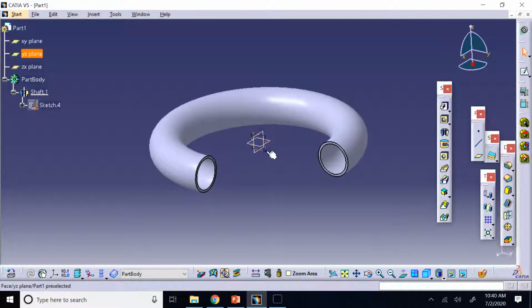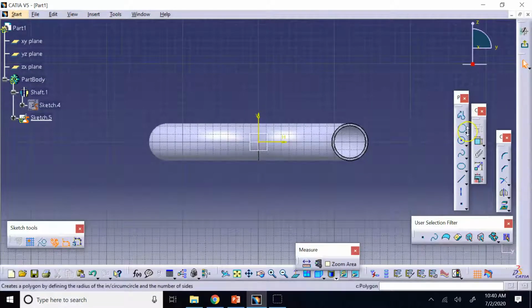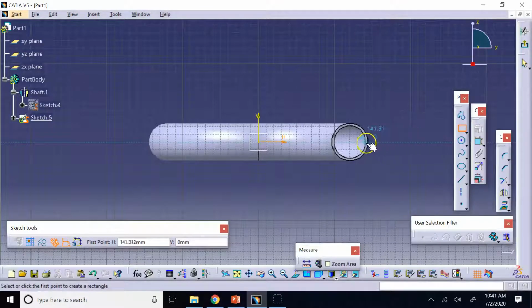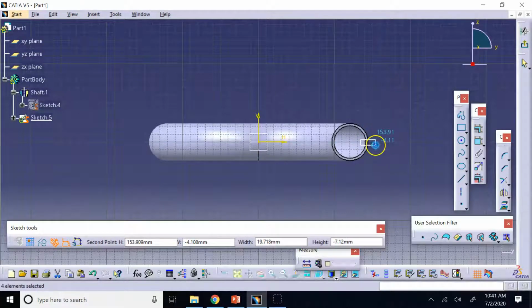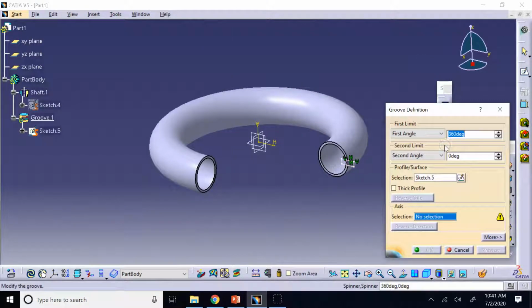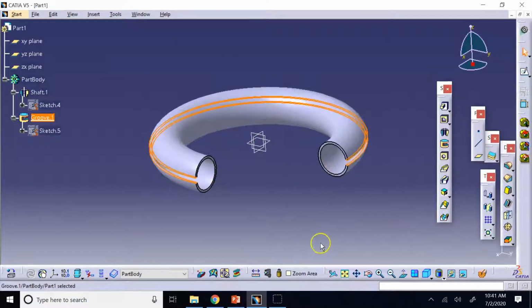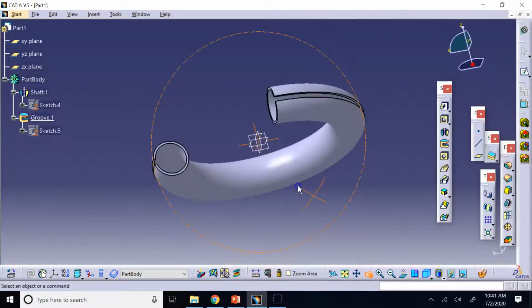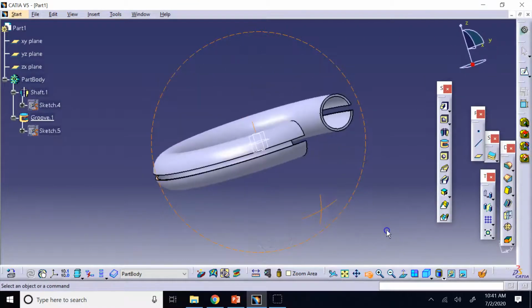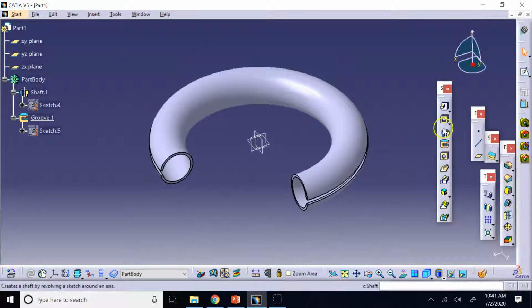For example, here, I go back to this plane, and here I draw a rectangle like this, get out, and I would rotate this guy about this axis, and then hollow out the rest of the material that I have created so far using this sketch. And look, if you do that, now you would get this guy, right? So this is the cut revolve, basically. So revolve and cut revolve.